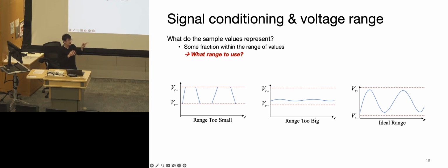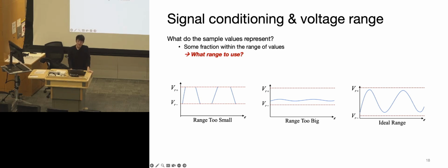Those ranges are typically provided to you in the data sheet. They will tell you the different modes of operation, or what the expected output range or input range is. So you can use that as the beginning reference, and then, depending on how you actually wired up your circuit or how you're sending your data, you can fine-tune that range.